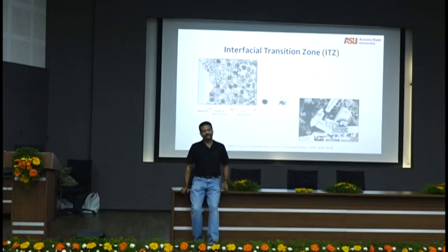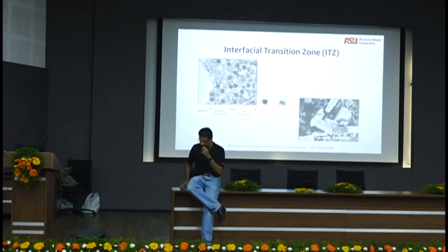Whatever you want. It really is an artifact. You have an interfacial transition zone. Basically, I'll give you the simple theory of it. If you have an aggregate particle, I told you what will preferentially precipitate on the aggregate particles? Calcium hydroxide. What's the shape of calcium hydroxide? Hexagon. When you put a bunch of hexagons together, are you going to fill the space completely?